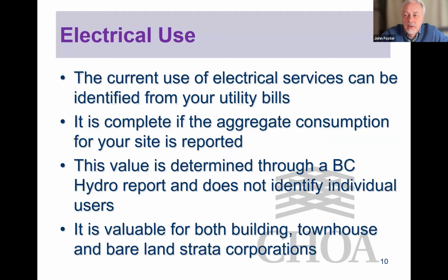But as people probably realize, gas boilers, domestic hot water, makeup air, the usual gas uses are often oversized by a factor of two or three. So what we're seeing so far is that people doing the reports are mostly not getting gas bills. So they tend to use that method where they just look at the size of it and convert that to electrical power.